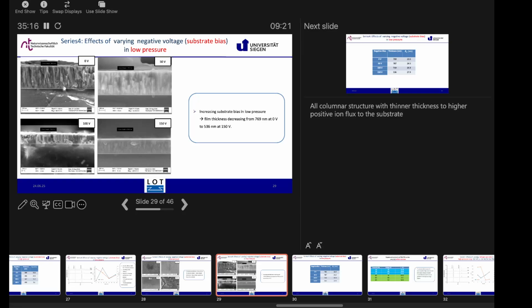How did you prepare this cross section? Because we need a cross section, we deposit on the silicon and then we cut the silicon. This one is from silicon. That's why we prepare copper and silicon for this synthesis. This is 0.5 Pascal. What is the pressure here? 0.9. Nitrogen concentration, how much? We hold around 9%. We vary only one, the negative substrate bias.